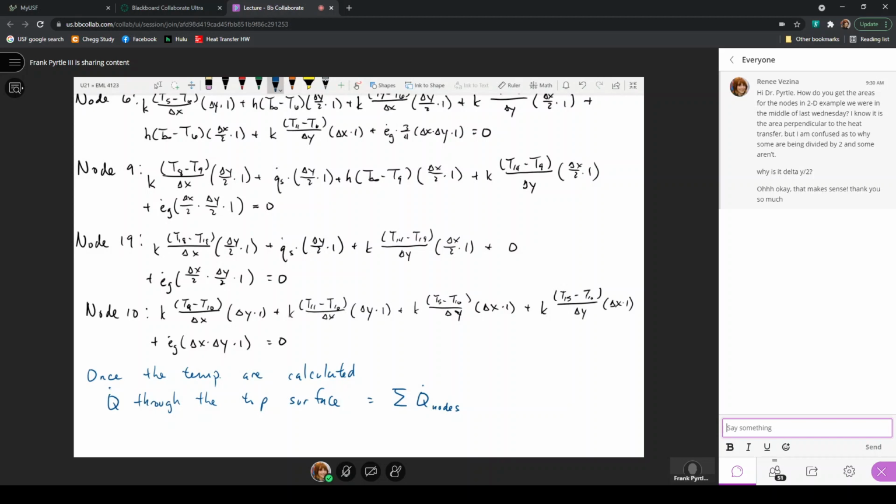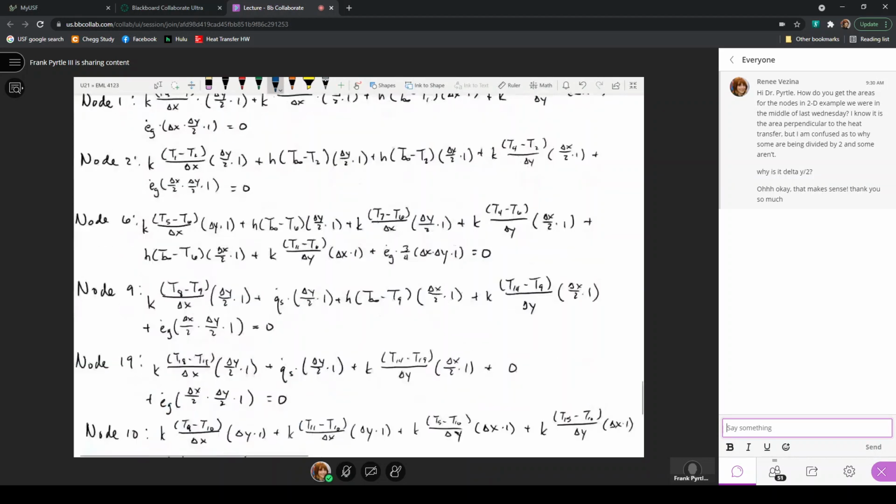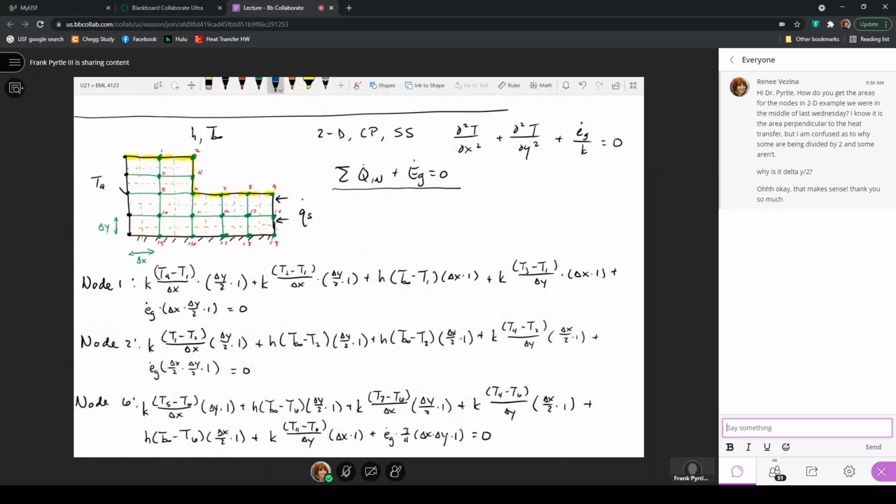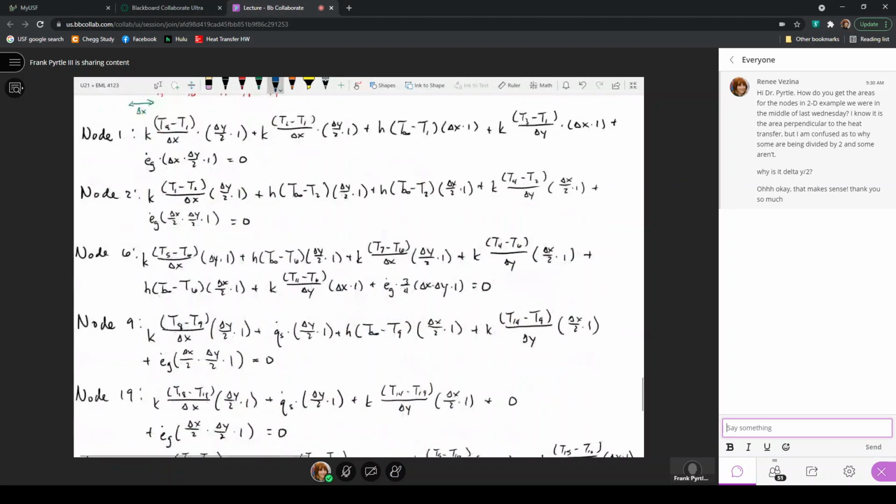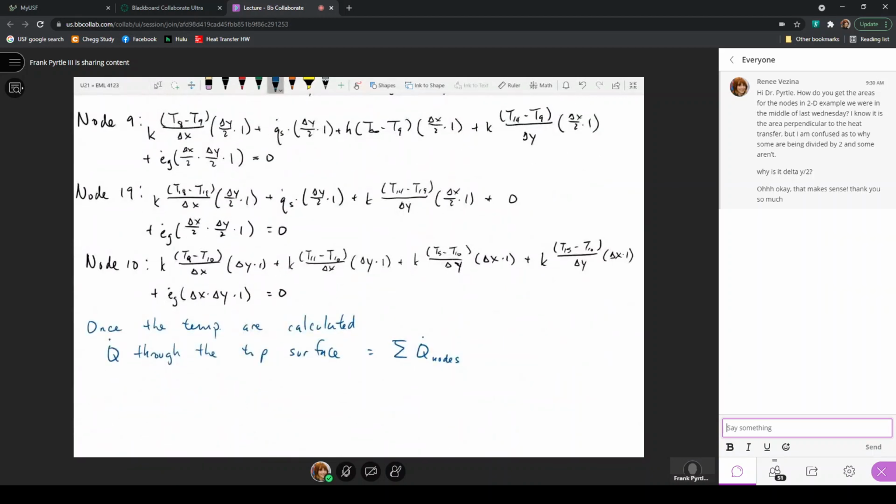So once I've actually determined the temperatures, here this would include the temperature that is TA for this section on the top surface, T1, T2, T4, T6, T7, T8, and T9. So the heat transfer rate from just this section that has a temperature that is TA, Q dot, and I'll write this. This is going to be by convection here.